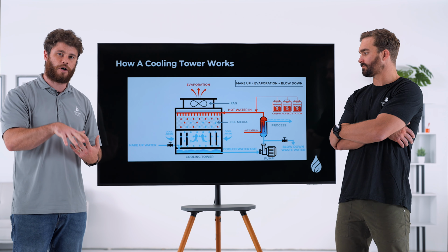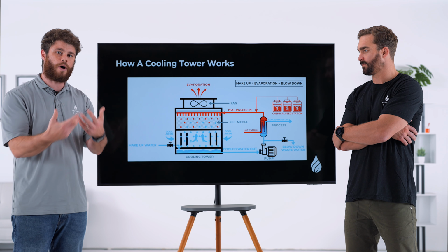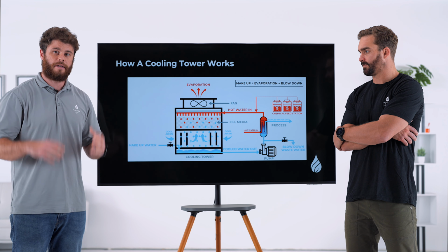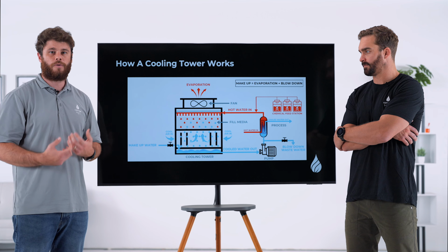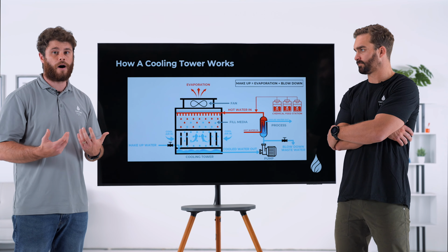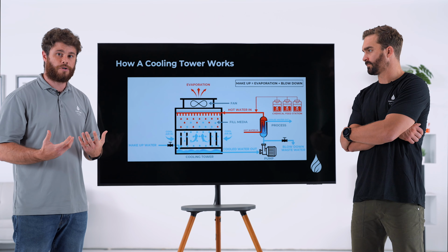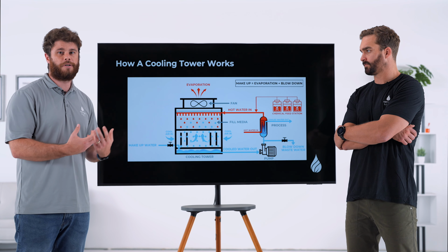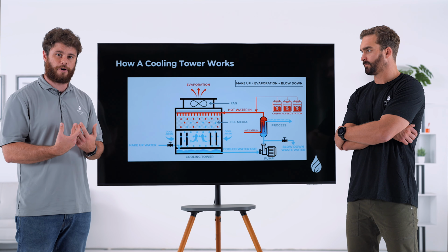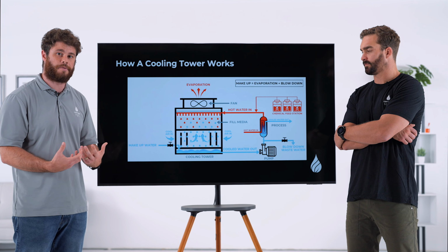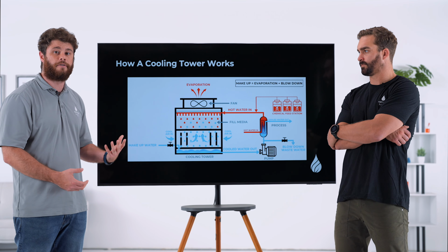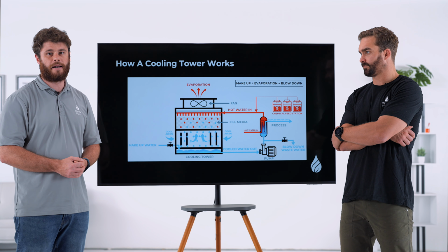As that hot water falls down the cooling tower and that cool air is swept up into the cooling tower, that cool air interacting with hot water will induce evaporation of some of that water, which will then leave through the top of the cooling tower. As evaporation occurs, the phase change from a liquid to a vapor will consume some energy and allow that remaining water that reaches the bottom of the cooling tower to be cooled and available for reuse. So instead of taking that water and sending it to the drain, we're sending it back to the cooling tower, evaporating a portion of it, and being able to reuse the remaining water.